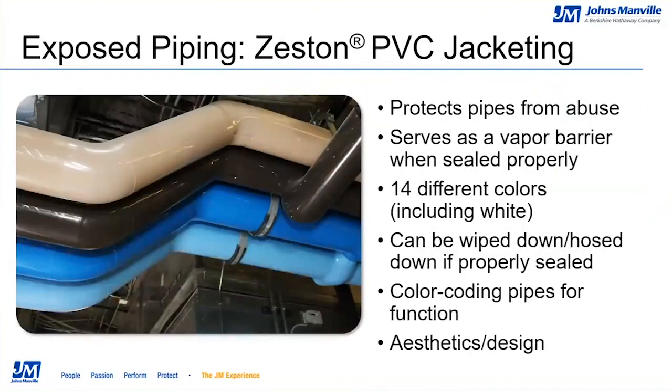So let's talk about jacketing options for a few minutes. Unlike HVAC systems, pipe systems can often be more accessible, either located lower on the wall or, in the case of a brewery, sitting on the floor itself. This makes an insulation system much more prone to damage. As a result, it can often be necessary to protect the insulation with the jacketing. Additionally, if you don't want the white facing of the insulation to be readily visible, PVC comes in a myriad of colors that can offer both abuse resistance and aesthetic appeal.